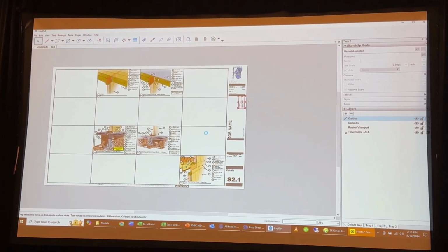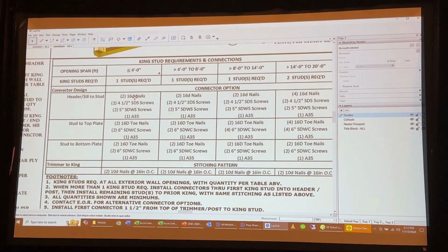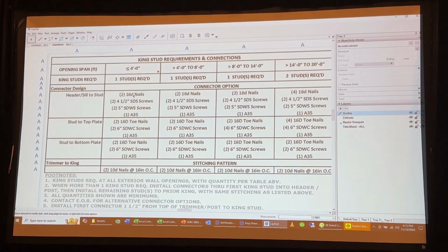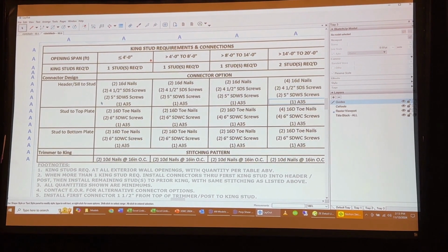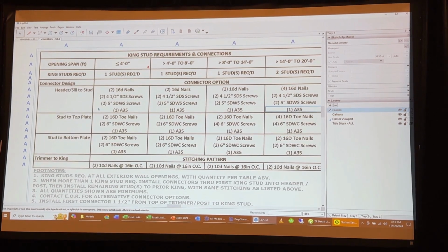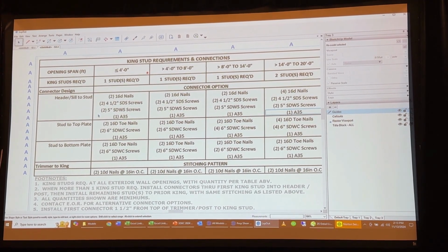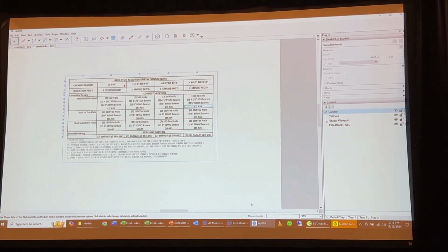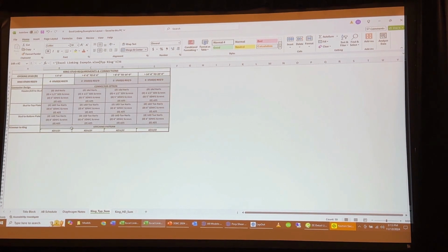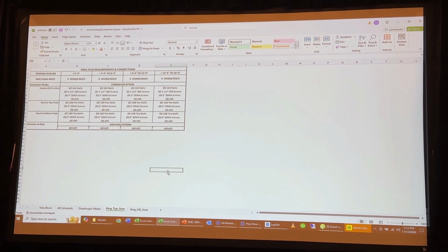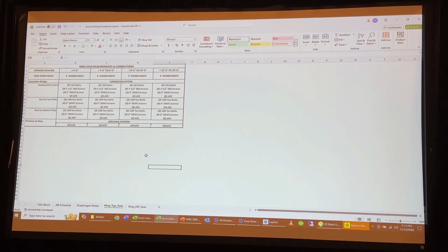You don't have to go into, say, this table, and imagine going in and by hand updating each one of these cells to the correct quantity, or even checking, if your drafter does it, or you want to double check your work. That's going to take a lot of time, right? So if you've checked your process in Excel, this is all based on our calculations. Then the one time you relink it, or if you change it and update the reference, it's all going to update in Layout for you.